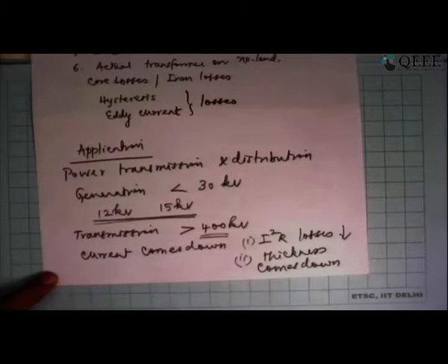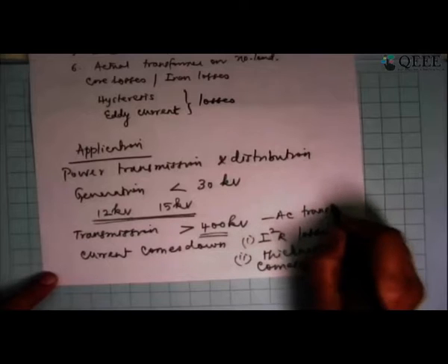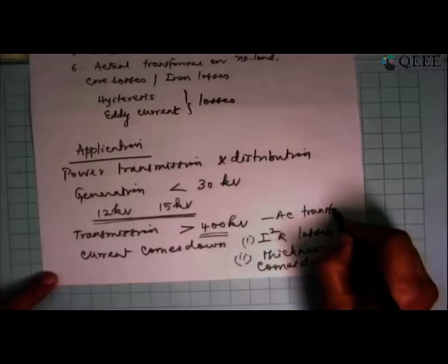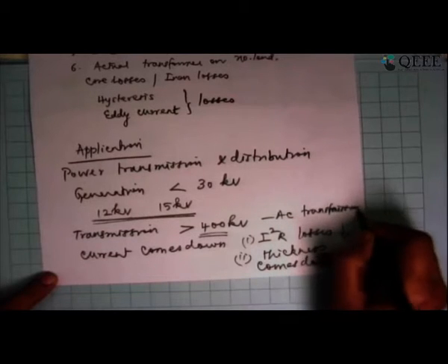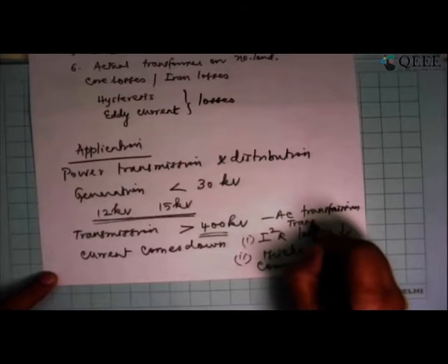So we are first of all looking at 12 kilovolts being stepped up to 400 kilovolts. From 12 to 400 kilovolts, it will be done with the help of a transformer. And it is all AC transmission. And the transformer will work only if it is AC transmission. So AC transmission essentially can be possible only with the help of a transformer.